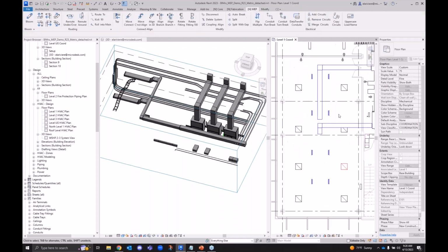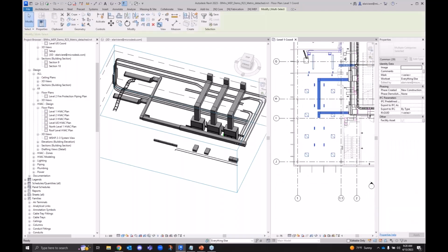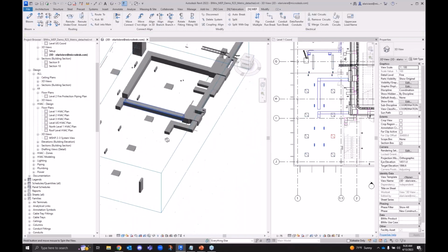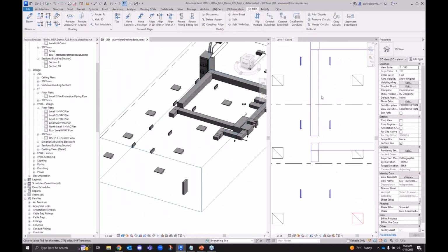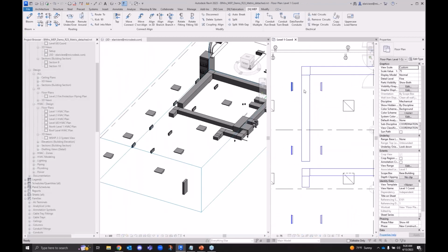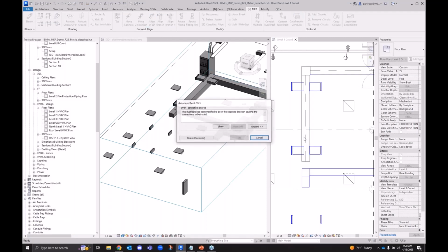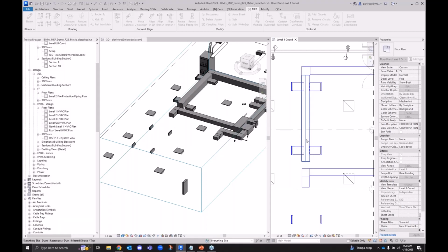Now let's open this up in the 3D view so we can see what's happening. But I'm going to do a lot of this modeling here just in the 2D view so you can see what's going on. If we want to go to any of those air terminals, we can bloom each of those out. We can use the align branch from before to make sure that everything is lined up center on center to allow me to do those connections. And just like I mentioned, if you have keyboard shortcuts, this gets even easier. And what about connecting it together? Well, let's use that trim extend to bring all those elements together afterwards.